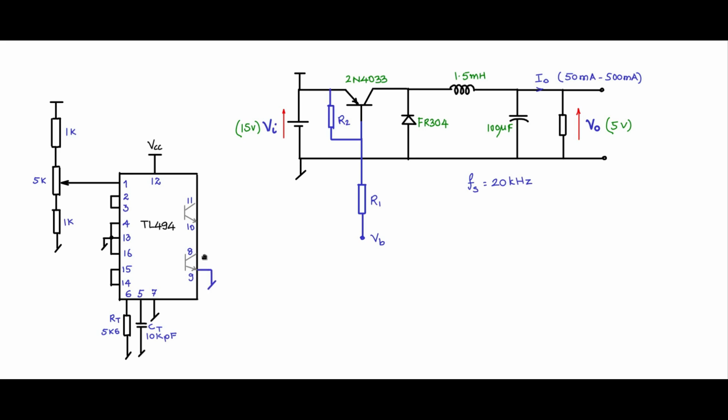Ground the emitter and the collector, let me connect it here. So that's it. You have a PWM generator IC where the duty cycle can be varied and controlled, and at this collector you will get the pulse width modulated waveform which is given as base drive signal to this PNP BJT, which will switch this buck converter and you will get the required output.